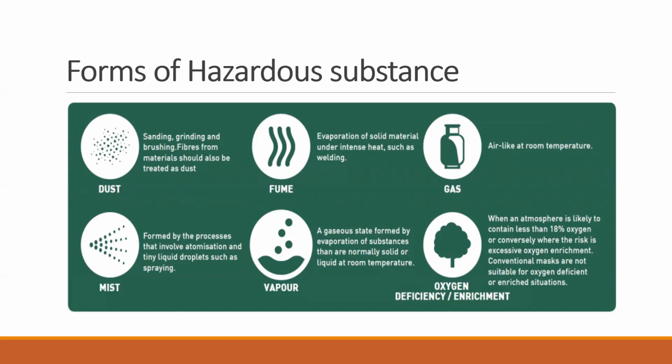and very common in construction or in the project sites is asbestos, because we have the asbestos sheets. In cement we have asbestos, in cemented pipes we have asbestos. In the construction itself, when we have demolishing activities, we have a lot of dust there, and we have asbestos available. In sand we have silica. Silica is also cancer causing, but asbestos is more dangerous as compared to silica.